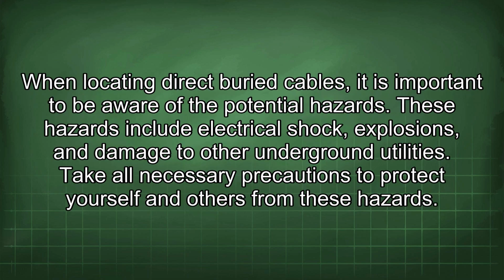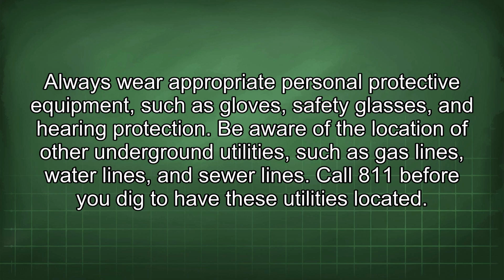When locating direct buried cables, it is important to be aware of the potential hazards. These hazards include electrical shock, explosions, and damage to other underground utilities. Take all necessary precautions to protect yourself and others from these hazards. Always wear appropriate personal protective equipment, such as gloves, safety glasses, and hearing protection.